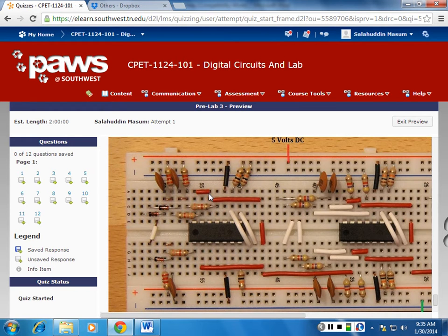So I'm just trying to show you how you can run the wire in a similar manner. So whenever you have to connect, let's say, pin 5 of one IC to pin 7 of one IC, you probably can do it right now, right? Also, the top and bottom ones: I know that some of you have bought breadboards from different manufacturers, so some of you may not have two rails here. These are called rails, okay? You probably have only one here and one here. That's enough.